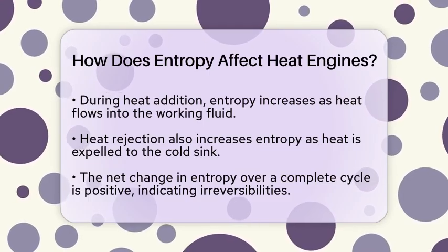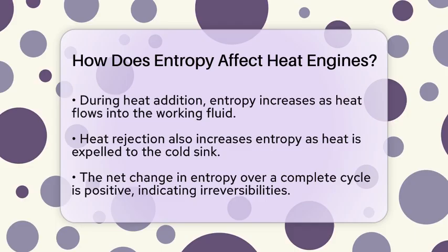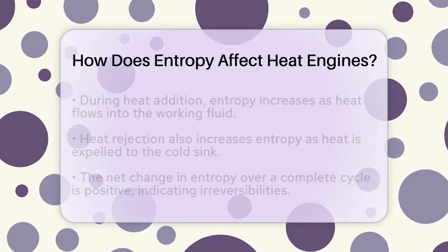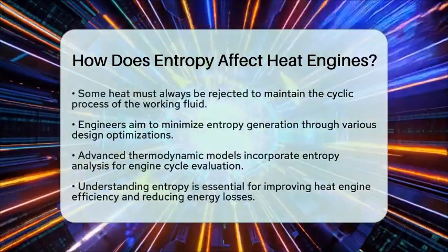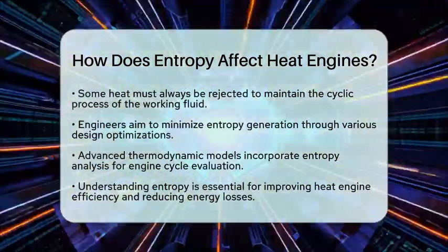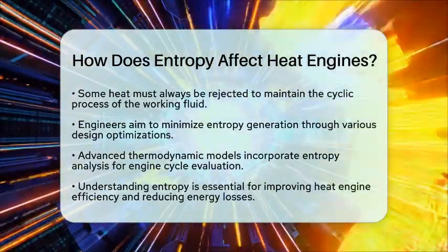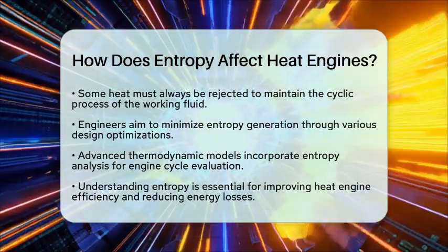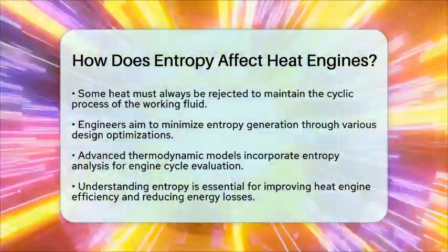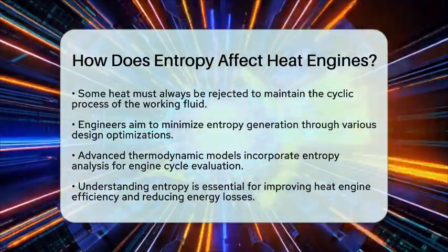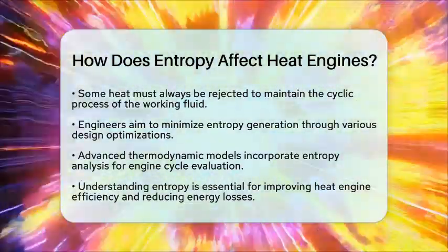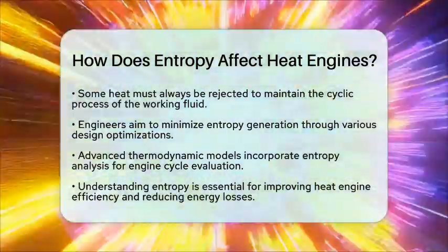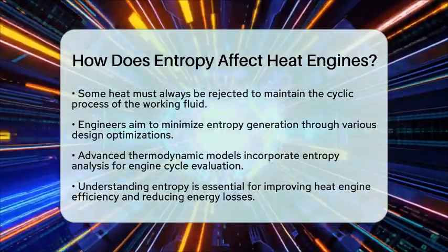From a mechanical engineering perspective, understanding entropy is vital for designing more efficient heat engines. Engineers aim to minimize entropy generation by reducing friction, optimizing combustion, and improving heat exchanger effectiveness. They also focus on controlling expansion and compression processes to get as close to reversible conditions as possible. Advanced thermodynamic models often include entropy analysis to evaluate and enhance engine cycles like Brayton, Rankine, and Stirling engines.